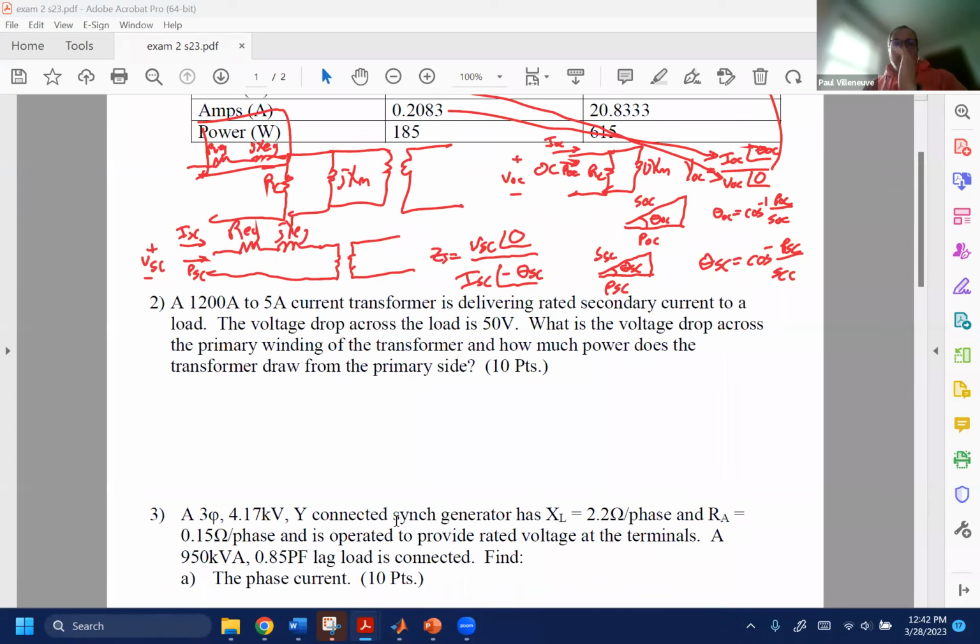All right, number two was a little bit of an interesting one where I tried to get you to think about how the real world actually monitors equipment. We talked about it from the perspective that you don't want to be running 1200 amps into somebody's control house. I don't know if people have seen that, but that's a lot of current. If you're pushing more than probably 100 to 200 amps, you've got some pretty sizable conductors, and 1,000 amps is more than that. So you're talking multiple conductors per phase, or cables without insulating material. So pretty big conductors for that.